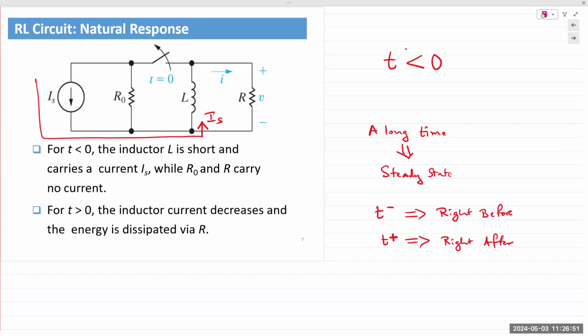Here's the important concept. Energy transfer cannot take place instantaneously, right? When the switch is flipped open, the source is disconnected. All of that energy does not drain instantaneously. You cannot snap your fingers and expect all of that energy to go out. Doesn't matter if you have all 5 infinity stones. It's not going to work that way. Current through an inductor cannot change instantaneously. That's the important point you have to remember. Current through an inductor cannot change instantaneously.